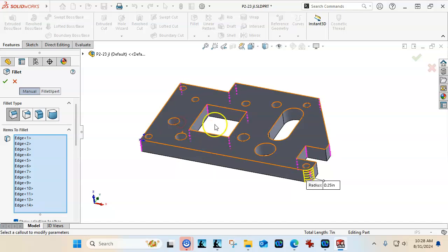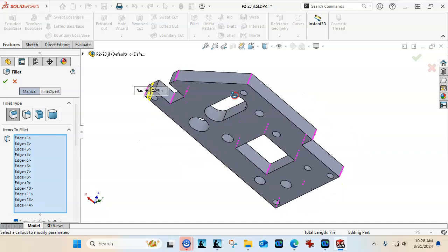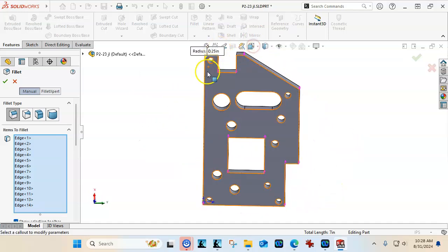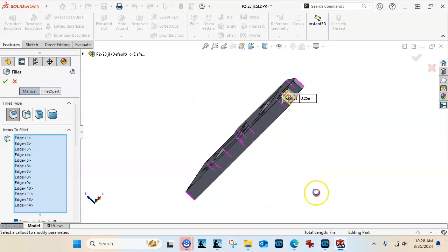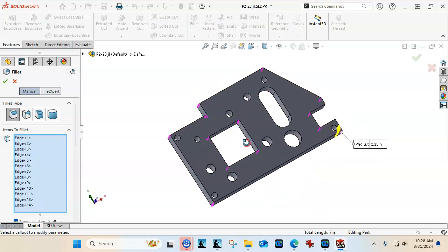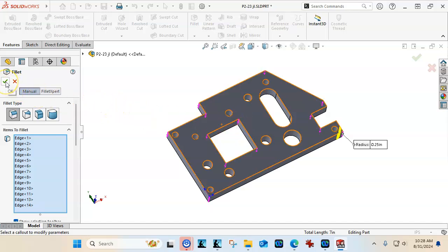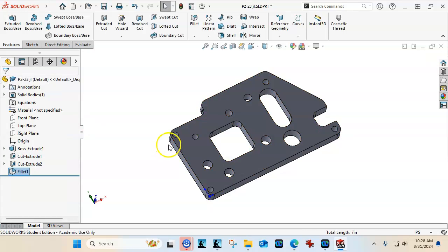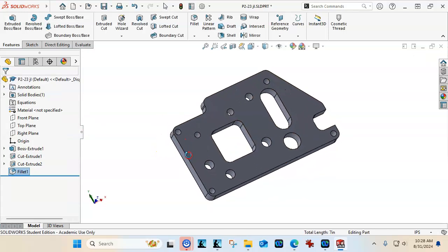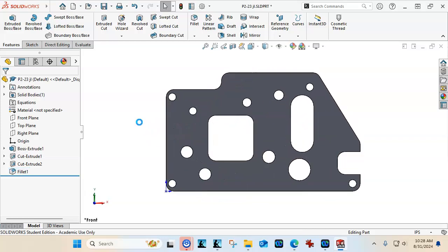All right. So the intention is that if I was clamping this down to a plate or holding it in a vise in the milling machine, the tool would be making its approach in Z. We'd run the pocket, run the slot, and then potentially run that notch. Now I could take this out in a second operation and set it up and nibble through there if those had to be square, but really I don't have a lot of choice with this one other than to do a corner relief so that there are reliefs for a square to get in there and the tool to get in there as well. So if I can get away with the fillet, I'm going to go that route.